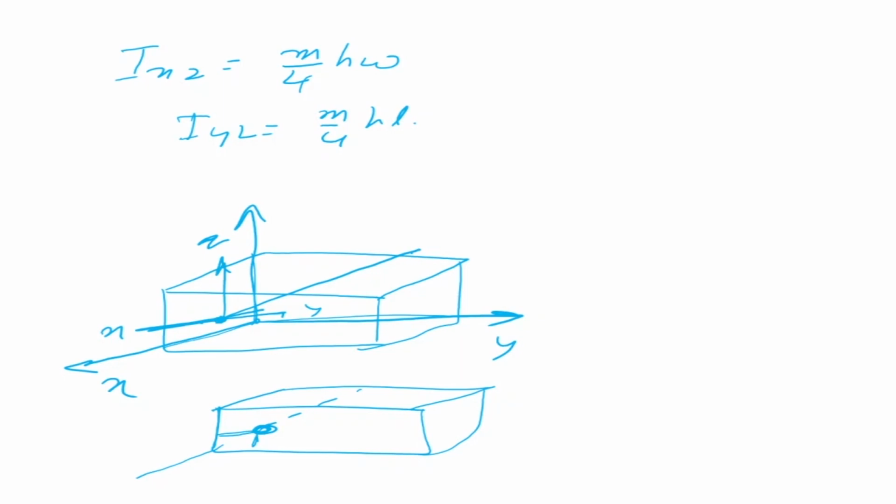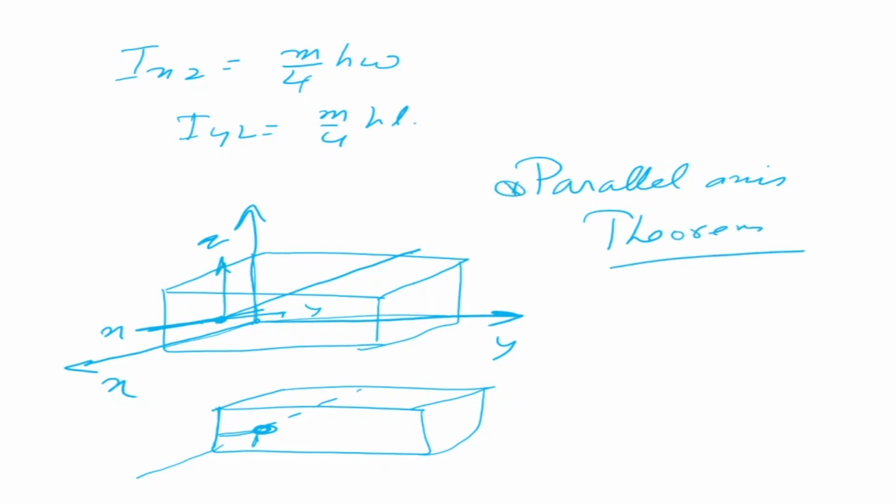So for that, we can use the parallel axis theorem, in case the axis is shifted. By using the parallel axis theorem, Izz, for example, is equal to Izz plus m into xc squared plus yc squared. So we can simply use the parallel axis theorem, and for this particular case, if the axis is passing through the centroid, I put it like this.